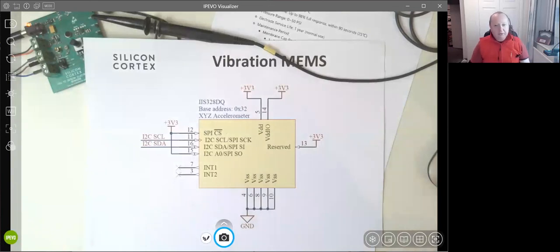So that's using a MEMS accelerometer. I'm currently doing it in the time domain. I'm using RMS at the moment. Because you've got positive and negative as things vibrate, I want to take out the negative component, so I'm using a root mean squared, which is quite straightforward to do.